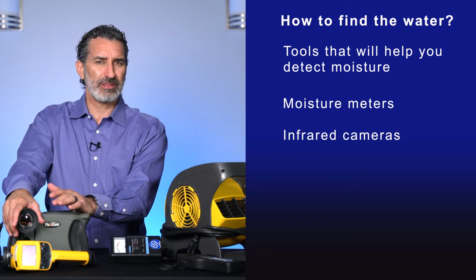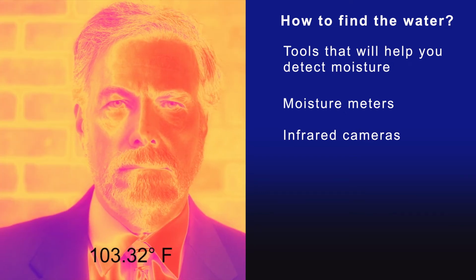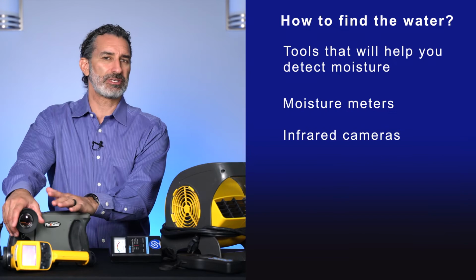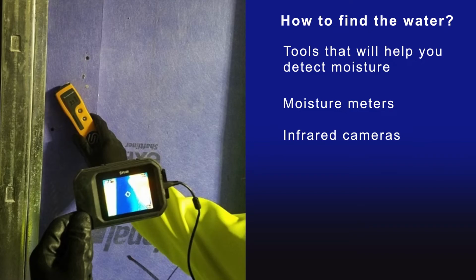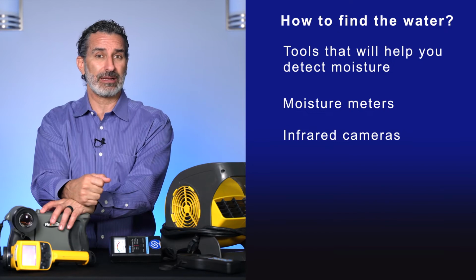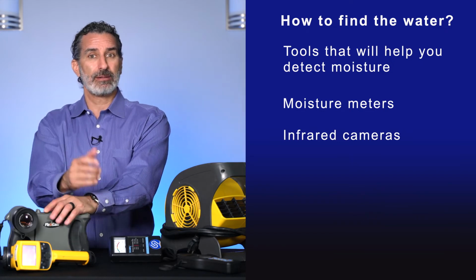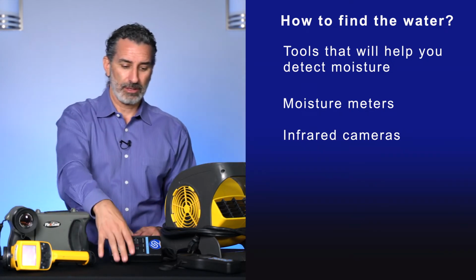On television, they will lead you to believe that these devices can see through walls. They do not. They measure the temperature difference at surface, but that can be used to your advantage because things that are wet generally are cooler, or in some cases, warmer than the surrounding building materials, allowing you to quickly identify what might be wet. You would follow that up with a moisture meter.